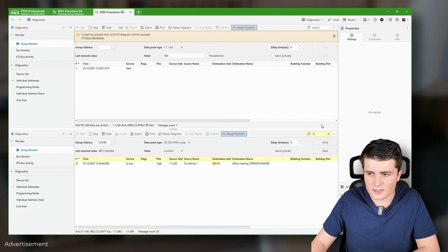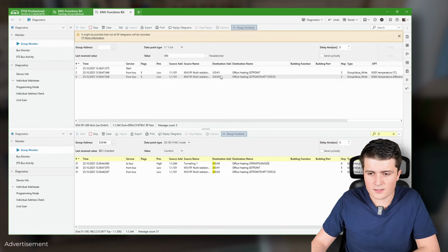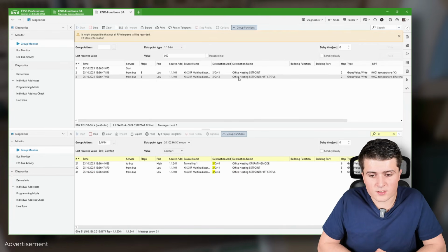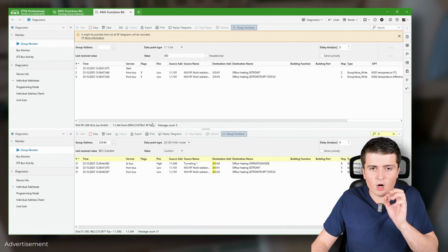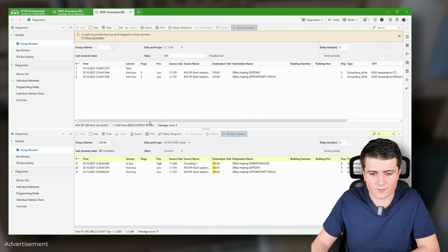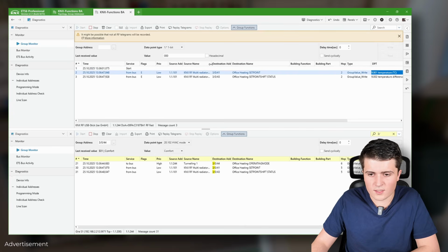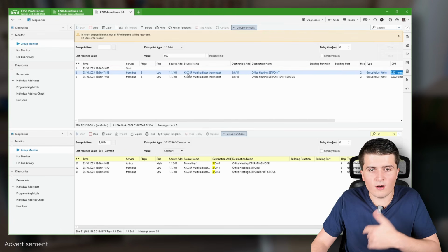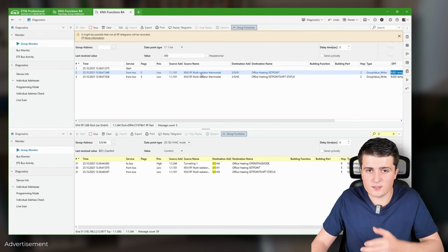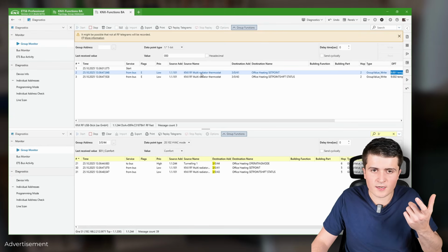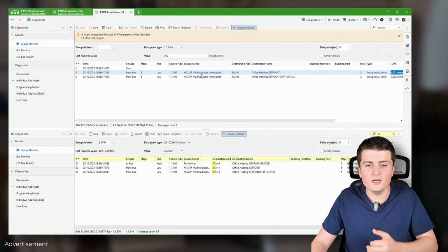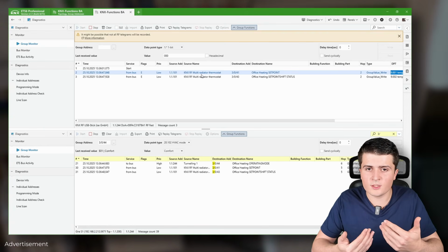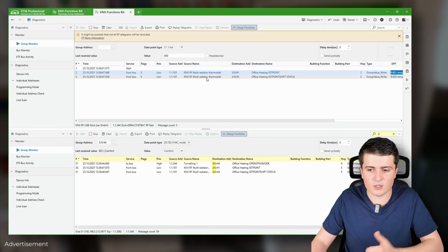And what you should see now is that here we get the response, because as mentioned, we only see the fast communication. Here in this case, office heating set point, so the response from our battery-powered RF multi-device, because remember, battery-powered multi-devices send in fast communication while they receive in slow communication, and therefore we only see the response.